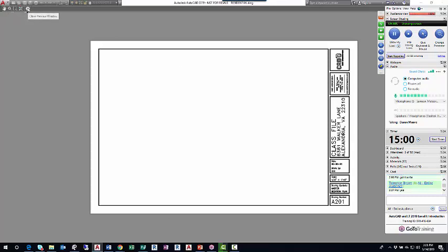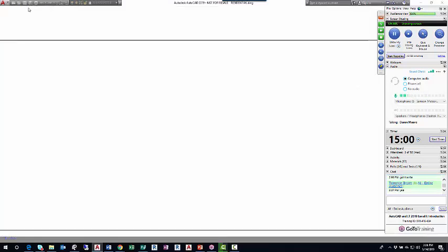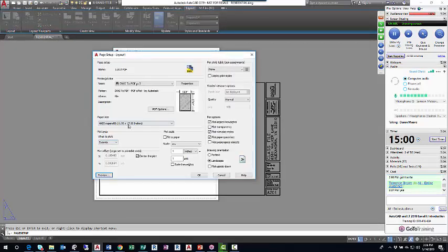If you find yours does not fit properly, I'm going to hit X. Then check the paper size. The paper size wants to be ANSI Expand B. There's several ANSI B, and there's a few ANSI Expand B. The Expand is a very narrow margin that allows you to print more. You have more printable area than just regular ANSI B.